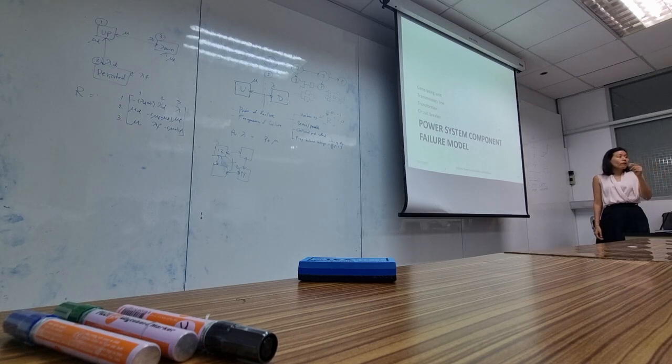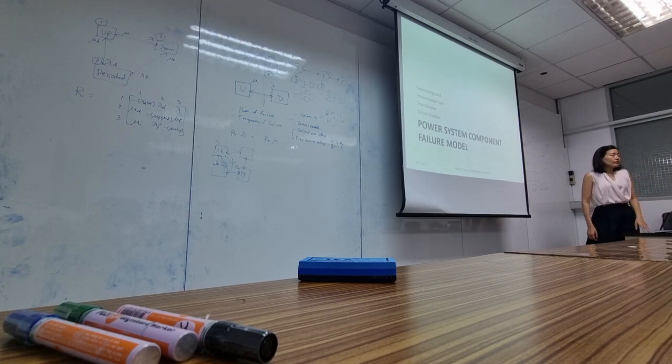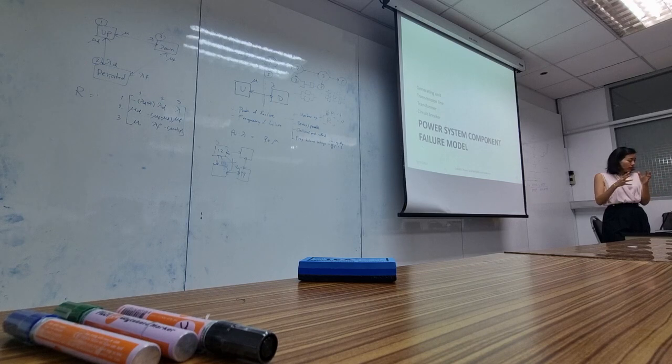The solution of the power flow will tell us how much power is injected at each node, how much power is consumed, we already know, right? But the solution of a power flow tells us whether the transmission line is going beyond its capacity or not, whether it will fail or not. Okay, so it's very important that you cannot just take away this power flow from the reliability analysis when you look at the overall system.